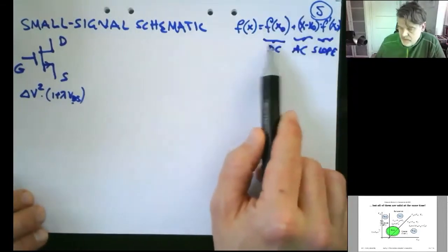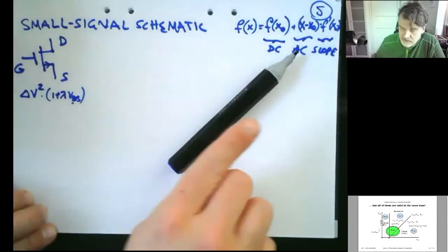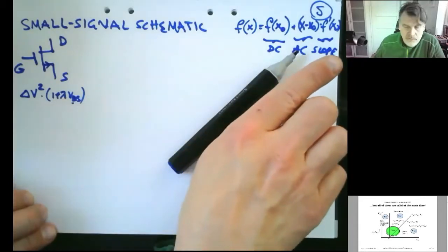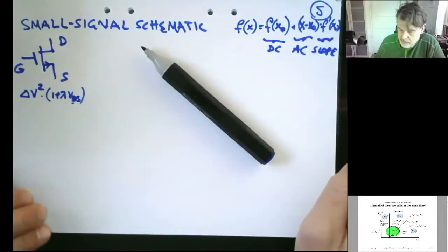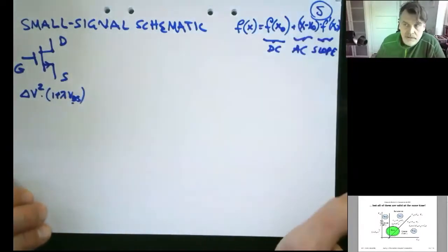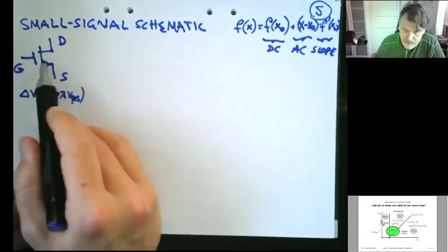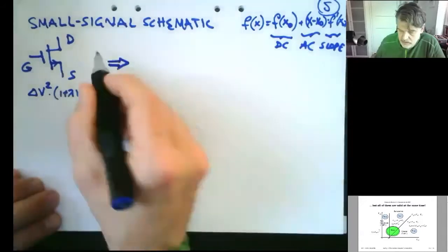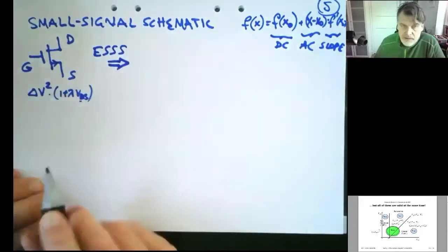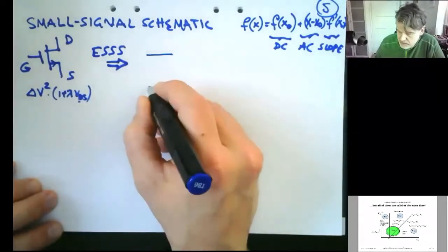But at least taking these two steps helps us to understand a little bit more about these directions. What can I increase to increase gain, or what can I decrease to improve the swing, or something like that? What can we read out from these equations? So the equivalence here is that this guy, a transistor, I can replace in the equivalent small signal schematic with a component which has nothing connected to the gate.